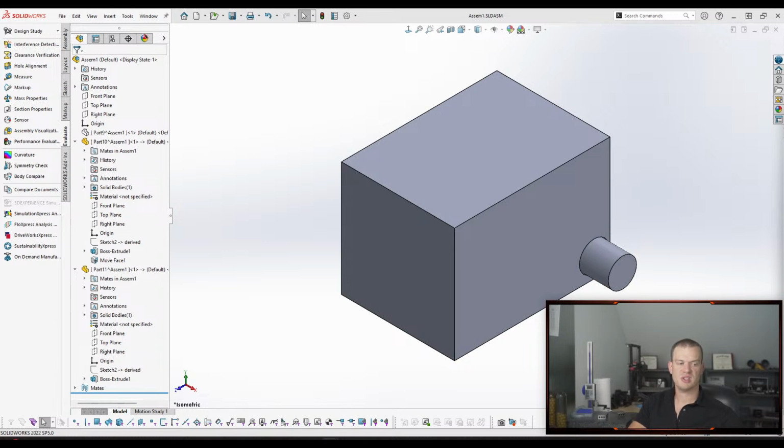Yeah, variable suggestion, or like pushing a variable down the tree is awesome, right? Another example that I've used in the past is draft angles. Say you design a part and you have a draft of 1 degree because you're thinking it's going to be smooth, and then the manufacturer comes back and says, hey, actually draft is 3 and your nominal material thickness isn't a quarter anymore, it's an eighth or something like that.